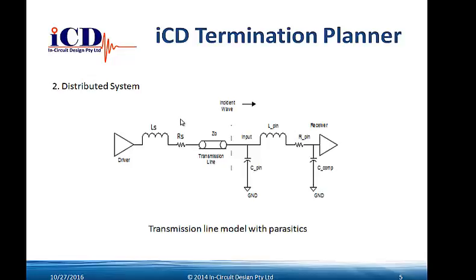And of course, the more receivers you put onto that transmission line, say if you have 3 or 4 receivers, the transmission line all driving 3 or 4 loads, then that capacitance of the component loads is all put in parallel, which tends to roll off the signal and decrease the rise time, which is exactly what a series terminator will do. So if we put more loads onto the transmission line, then we need less series termination, basically.